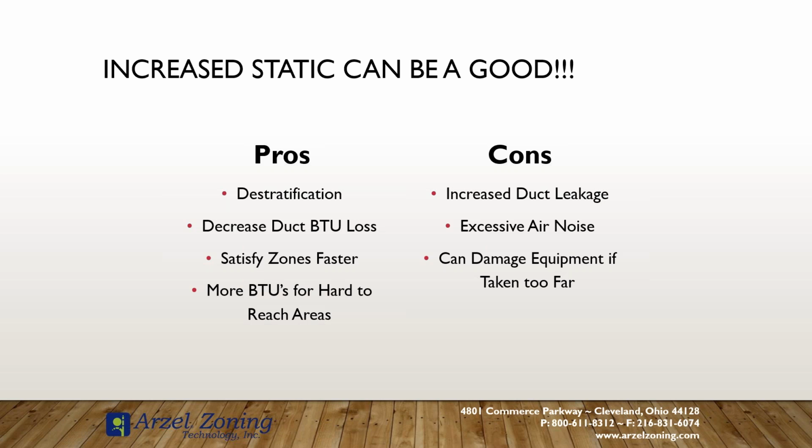It causes more mixing, more churning of the air, and it helps to reduce those hot and cold pockets within that area. Very similar to what you would have with small duct high velocity systems. They move air at a high velocity, they forcefully churn the air within that area, and it helps to destratify. It removes those hot and cold pockets because it churns the air at a more effective rate than what you have with a standard velocity system.